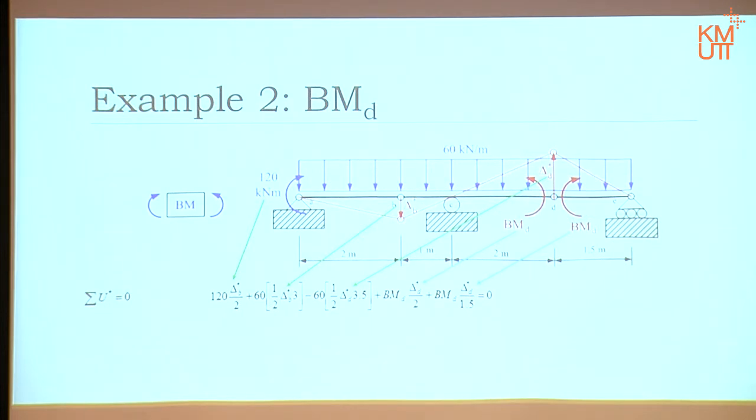Now, even though I have designed delta beforehand to reduce the amount of unknowns, the one that we have to eliminate... However, this time we still have delta B and delta D. So what I have to do is link delta D and delta B using similar triangles, that triangle and that triangle. Therefore, I can work out that delta D is equal to 2 delta B. We agreed? In that case, I can change delta D into delta B.